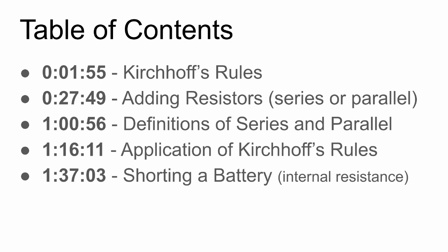We use Kirchhoff's rules to derive the resistor addition formulas that you may already know. And as we get into more general application of Kirchhoff's rules, where we encounter situations involving resistors that cannot be added as a series or parallel, we make our definitions of series and parallel precise, so that we don't accidentally add resistors that we shouldn't. And we wrap up with an example of how we can model batteries in circuits more realistically.